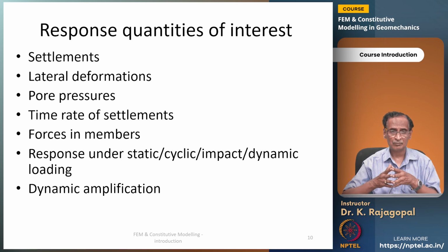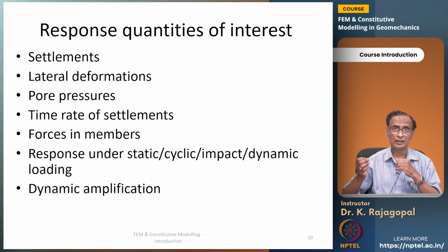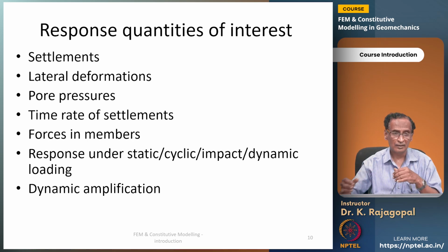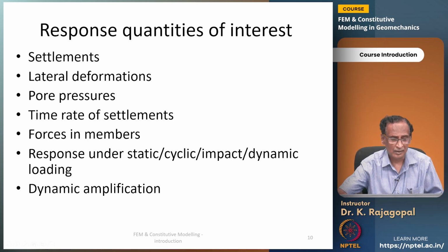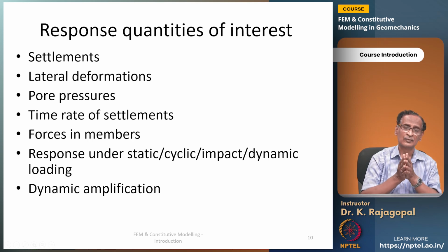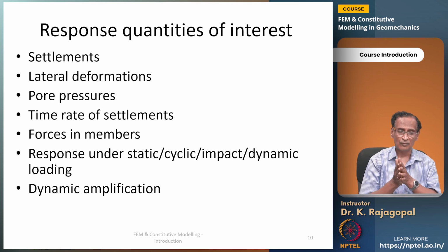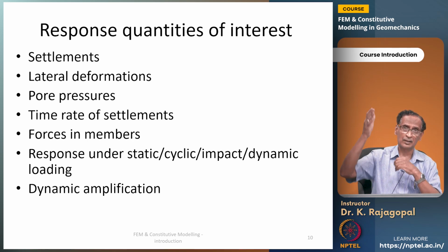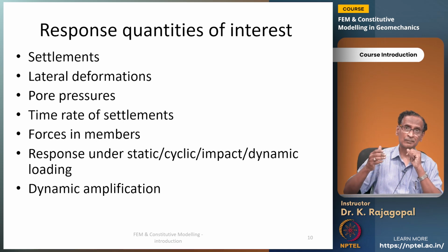Then what are the different responses that we are interested in determining through this analysis? Obviously, the first thing is we would like to know, if you construct, what will be the settlement, both total and differential. Then what could be the lateral deformations, especially if you are making a deep excavation.